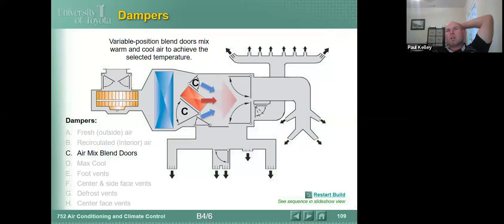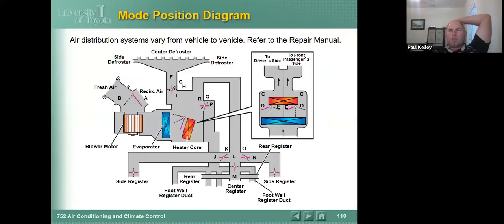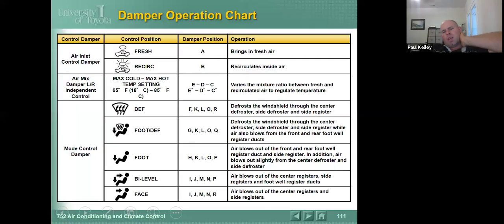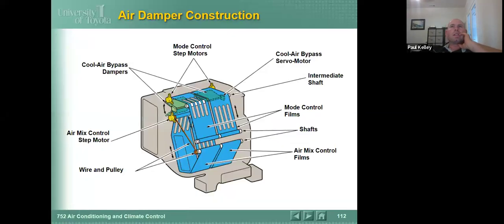So some of this is some of the later things that we cover. Cool. So this mostly gets it. You can see on the dual zone, you'll see distinctly there is a temperature door for the driver and a temperature door for the passenger. Totally separate, independent, right? So that heater core has to slide through a separator, and air is isolated for the passenger and isolated for the driver. Cool, not real crazy. I think you guys get it.